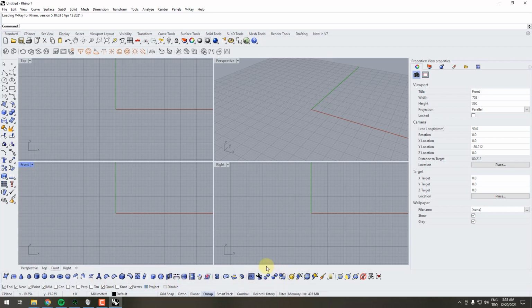Second to the last quarter of the menu bar, we have some technical commands such as quad mesh for creating the surface with a new structure, or convert objects to NURBS for switching between SubD surfaces and NURBS surfaces. We will be using these commands rarely, but of course if you have a look at these three commands, we have fill SubD hole, extrude SubD, and offset SubD. We will be using these commands more regularly, and we can say that these are SubD versions of the regular fill hole, extrude, and offset commands.